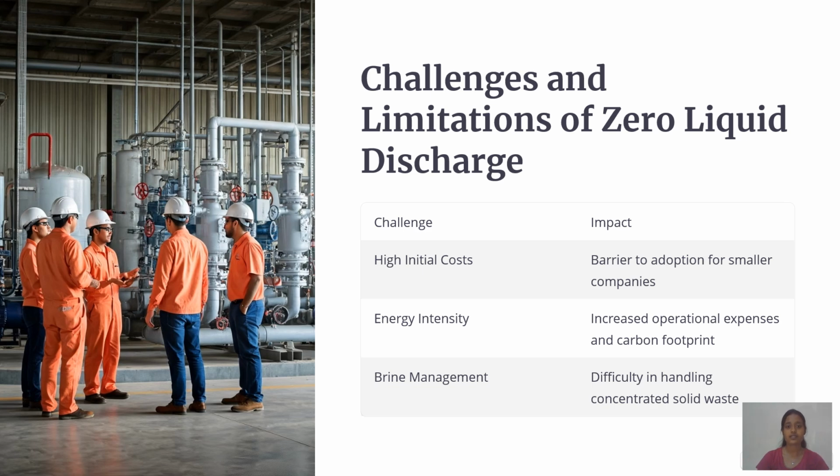So next is the challenges and limitations of zero liquid discharge. So this will offer environmental benefits also, but it faces challenges including high energy consumption, operational complexity, and high cost is another one. So the evaporation and crystallization process are energy intensive, which can increase the operational expenses, and greenhouse gas emissions can also be emitted.